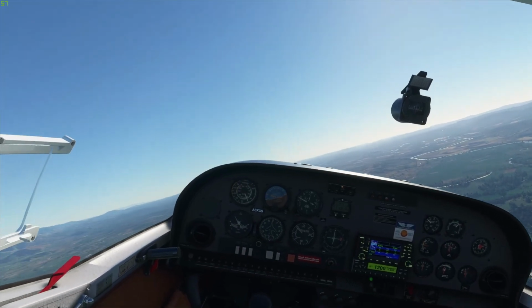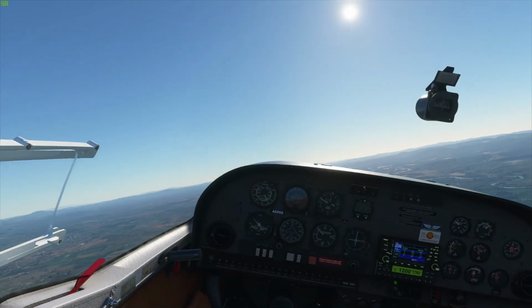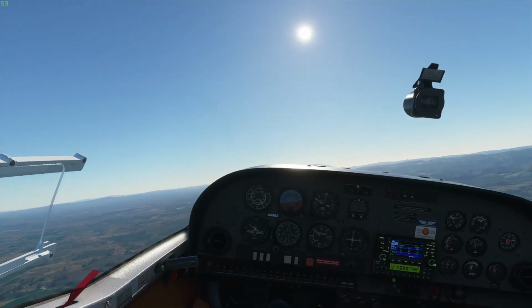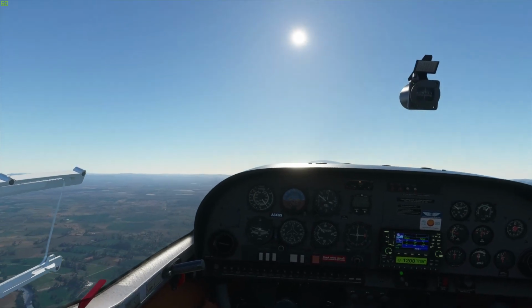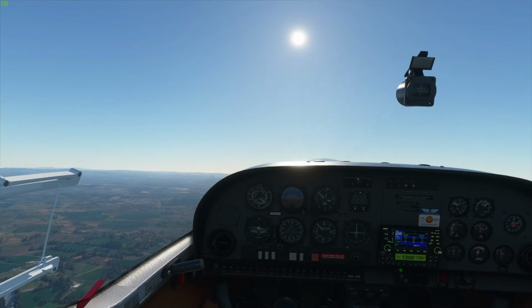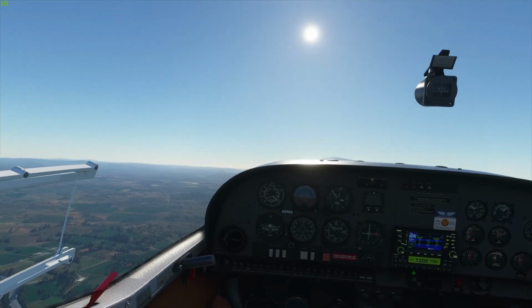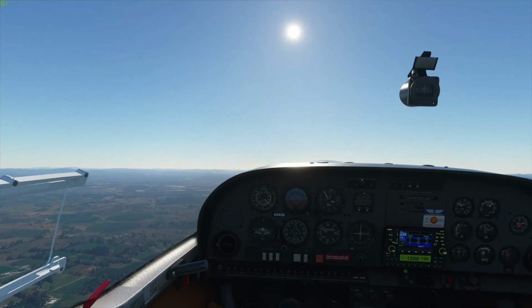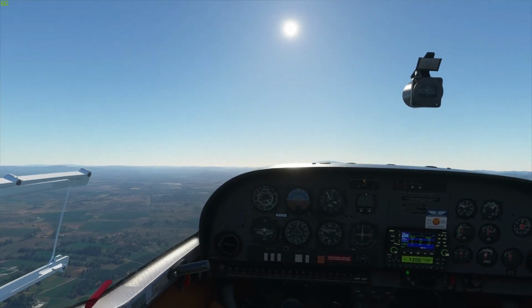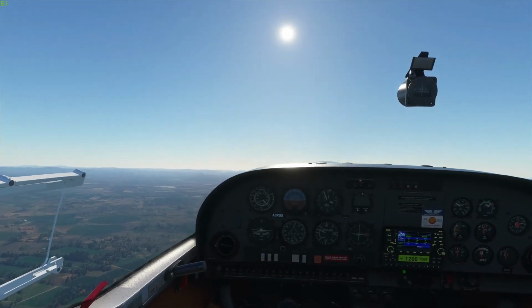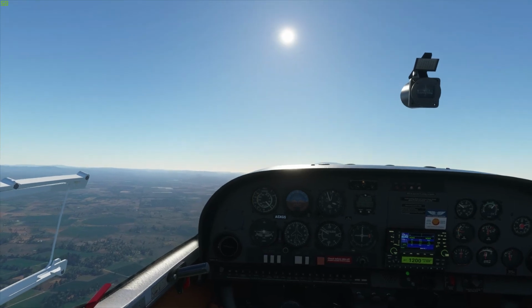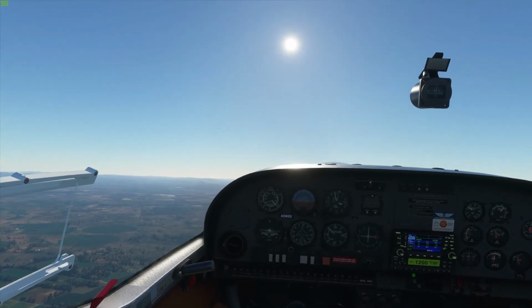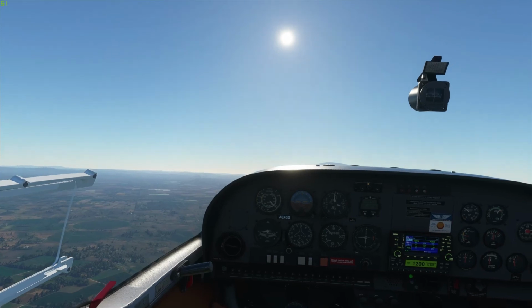Yeah, so it flies pretty slow. I should have kept it more level. We were descending there, but there was no adverse characteristics. It didn't drop a wing to the left or the right. It just stayed pretty much neutral. And it recovered virtually as soon as I released the back pressure on the stick. So that's what we'd expect to see. It did start to feel quite mushy. By mushy we mean the control effectiveness really drops as you get close to the stall.